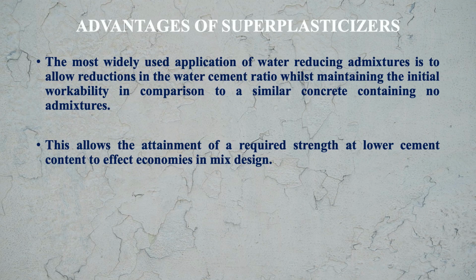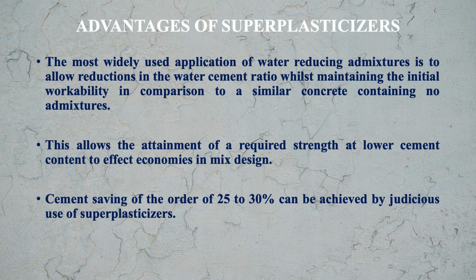This allows the attainment of a required strength at lower cement content to effect economies in the mix design. Cement saving of the order of 25 to 30% can be achieved by judicious use of plasticizers. So that way the use of superplasticizers makes concreting economical also.